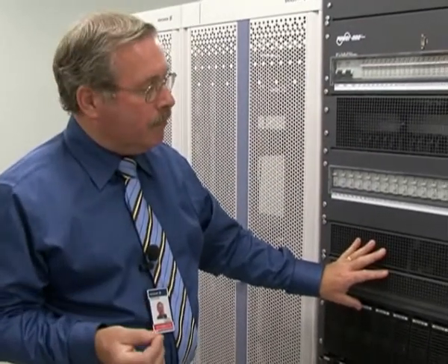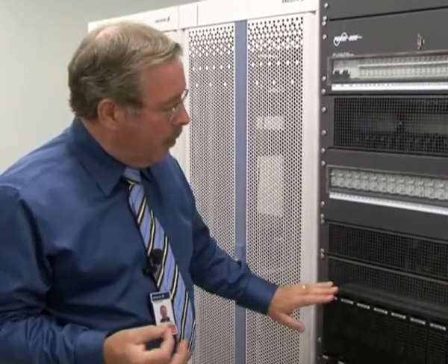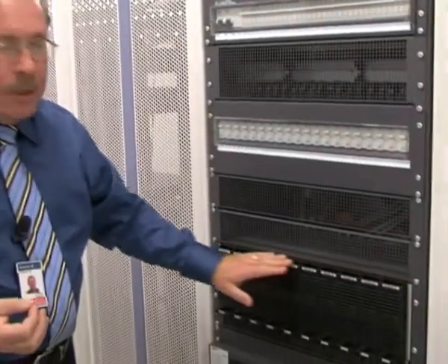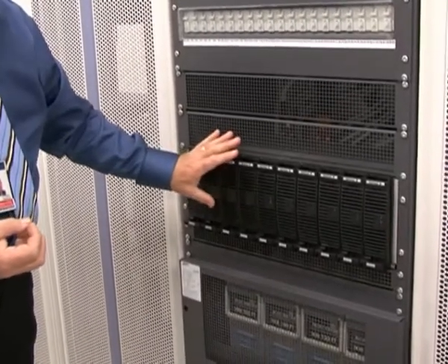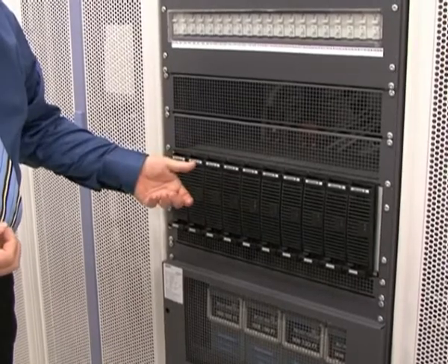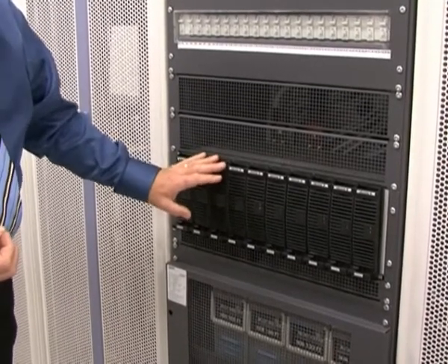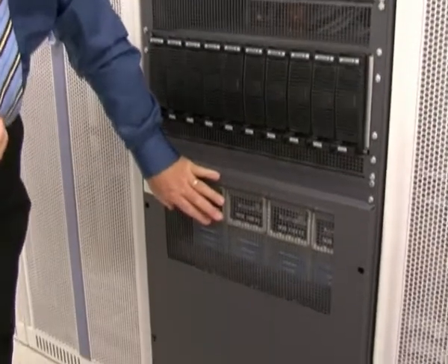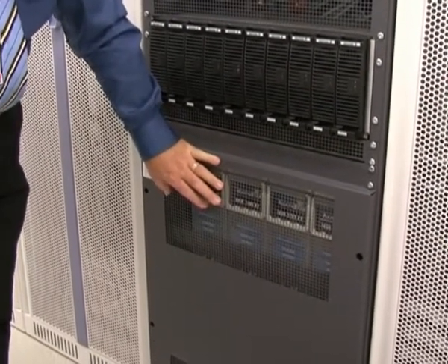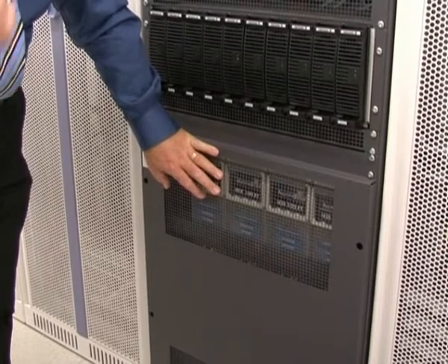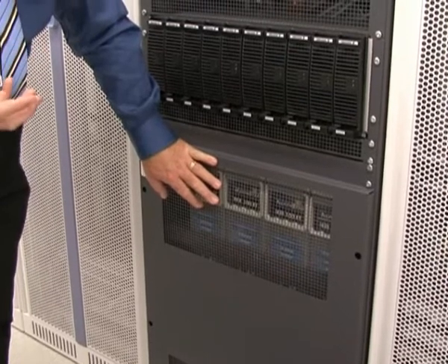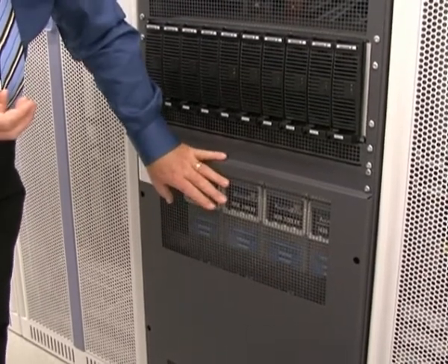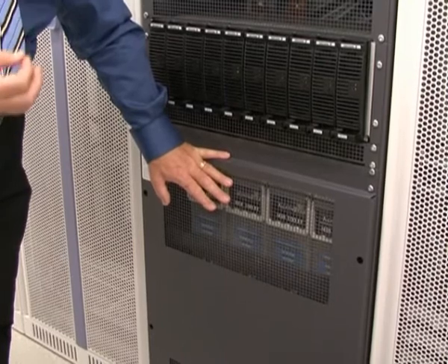This cabinet is an example of the core power solution. In this particular example, we have got a bank of rectifiers which take the AC power source into the cabinet and it converts it into DC and a lower voltage. This is then combined with backup batteries, and so we can provide a nice continuous and stable DC source to power external equipment. In the event of a power failure, the DC batteries will continue to supply the external equipment.